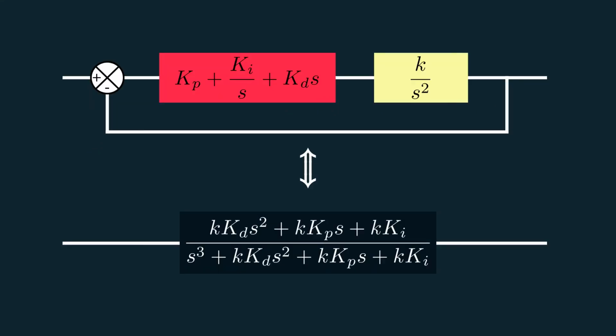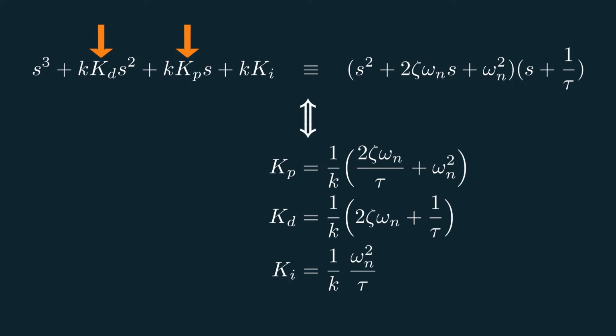The PID controller is designed using pole placement. The proportional and derivative constants are computed to stabilize the system and impose a given value for the damping ratio and the natural frequency, which shape the overshoot and the settling time of the step response. The integral constant places the third pole sufficiently fast to neglect its effect on the dynamics, but not too fast to avoid motor saturation due to sudden jumps in the control effort.